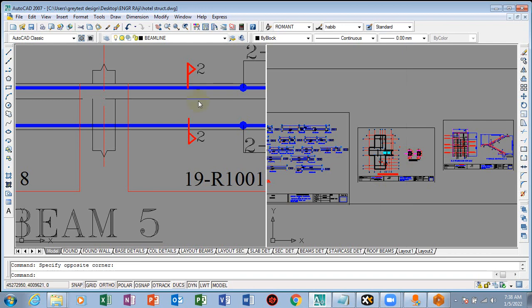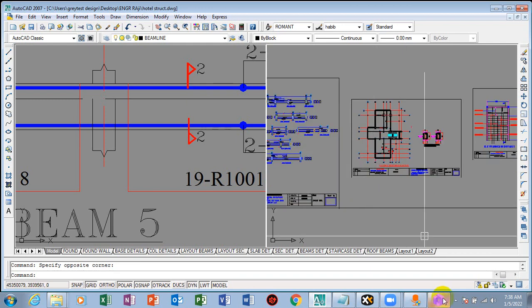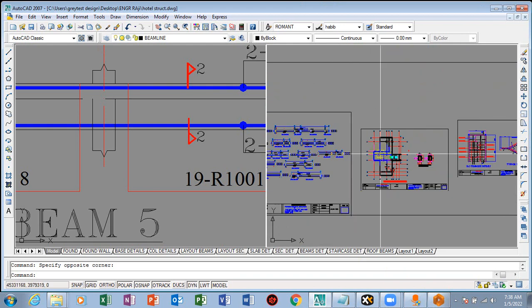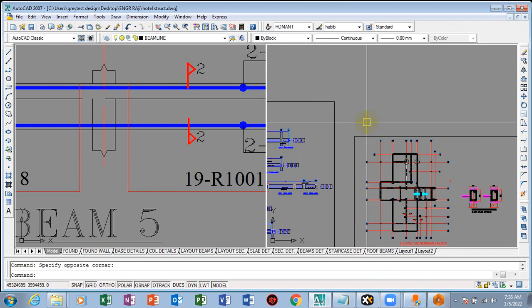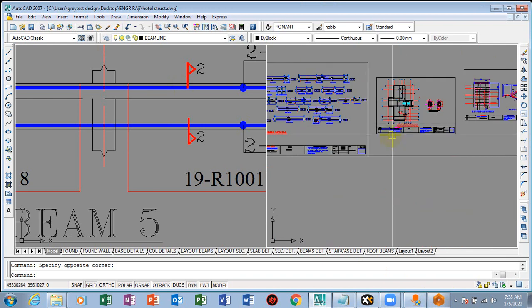No, it's from your design now. While you are doing your modeling, you don't use 230 by 450 at that level anymore. You change it to 230 by 300. When you are at your roof level, you change the beam. Instead of using the normal dimensions or cross sections of your beam, when you get to that level, instead of 230 by 450, you type in 230 by 300. As simple as that.